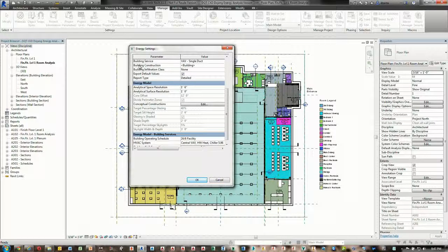The way I would handle that is I would work from the conceptual massing environment level, where you build your mass objects based upon the space usage. So maybe I have a space here that's for retail, and a space over here for mixed use, whatever. As you build the mass objects this way and treat them by usage, and even by the function of zones, then you can separate them and it'll give you a better report than trying to do it this way.